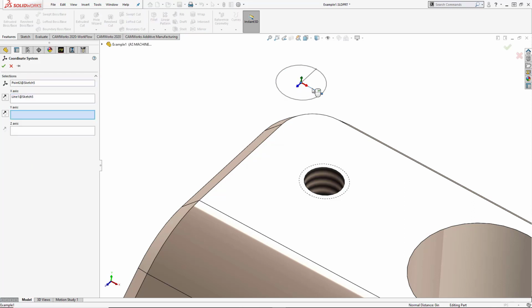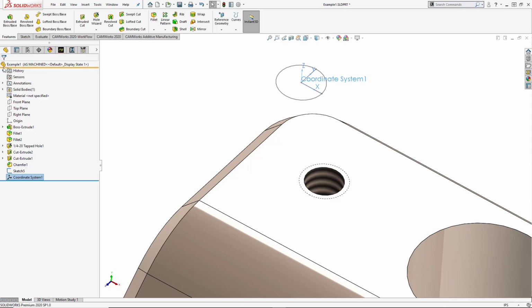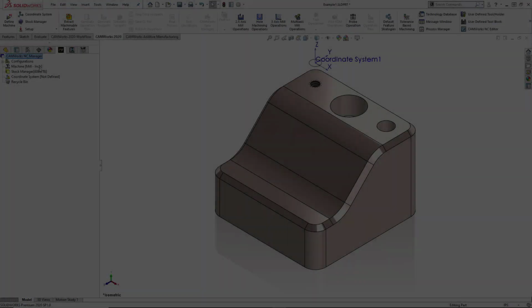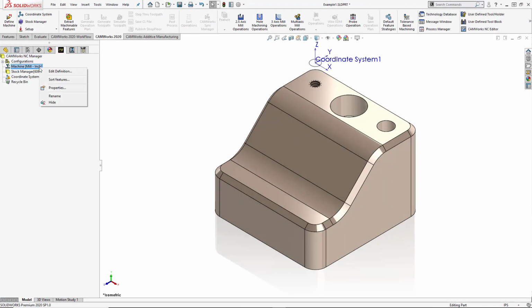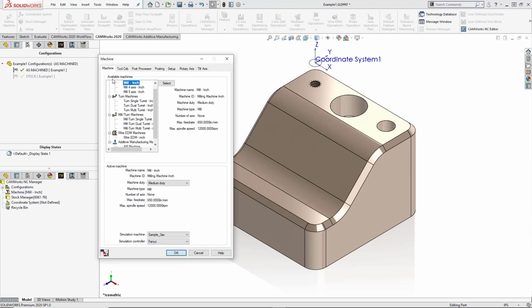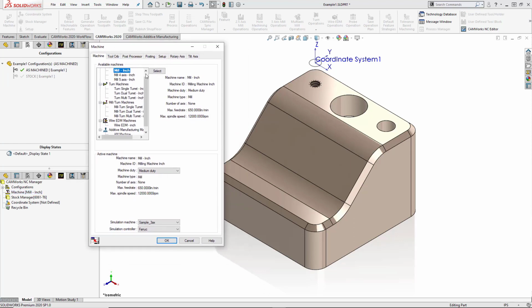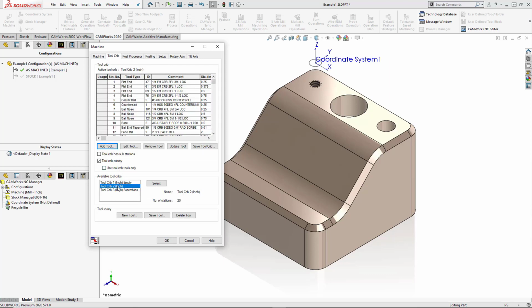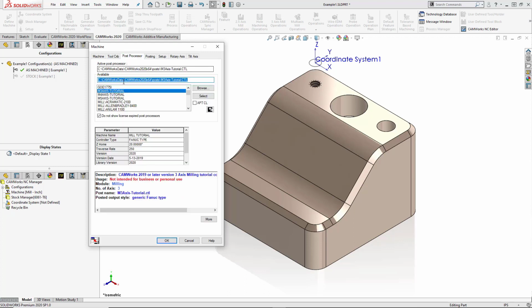This important SolidWorks feature refers to the home point or main zero position of your machining center. Simply put, it establishes how your model is virtually positioned on the machine table bed and relative to the machine spindle. Not only does it define the default G-code origin, it also defines the X, Y, and Z machining direction and acts as a reference point if subroutines are used.